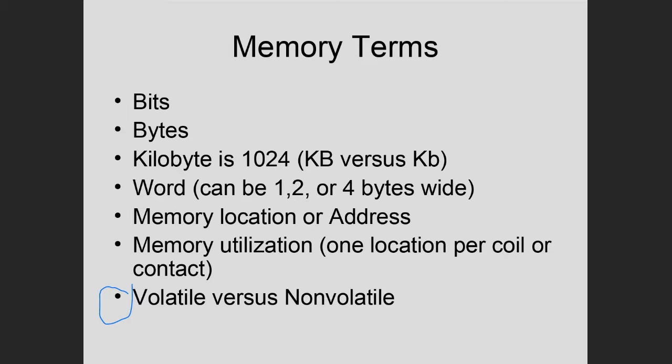Well, we mentioned we'll talk about addressing, but if you think about the cells, think about a register. Even though it's a physical device, think about it as being like one row of an Excel spreadsheet. Maybe you have 16 cells in the row, and you can put ones or zeros in there. Each one of those cells can be mapped to a particular screw terminal on the input module, and then you can connect the switch to that. If the switch is open or closed, it'll put a 1 or a 0 in that particular cell it's mapped to.